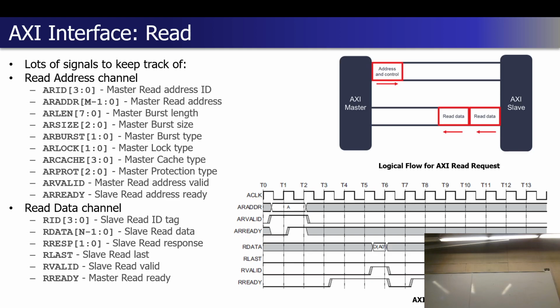This one doesn't show the burst, but there are two stages associated with that transaction. There's first the handshake of the AR valid, AR ready signals. As the sender or the initiator, I set AR valid high. I know I'm good to go once I check and see that AR ready has also gone high. This shows AR ready going high. This is the rising edge of the clock in our design. The receiver has checked that AR valid has gone high, does some sort of if statement, some sort of latency, and then says AR ready is high. At the next rising edge of the clock, my interface detects that AR ready is high. I now know I've transmitted that address information.